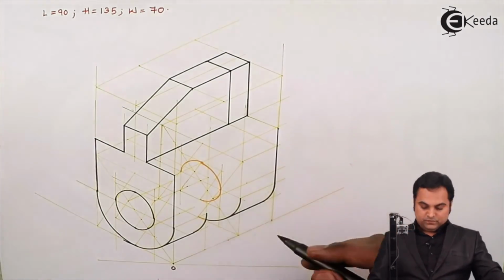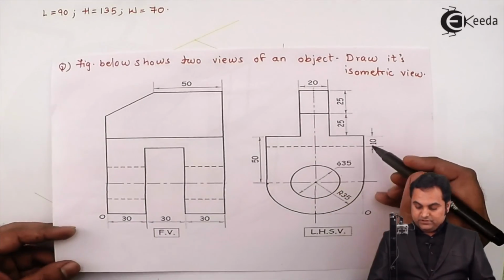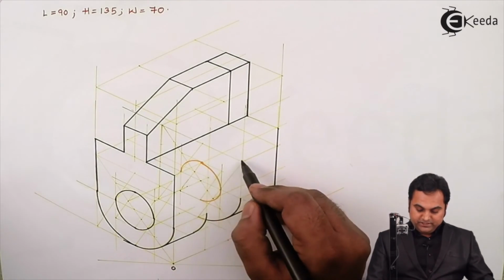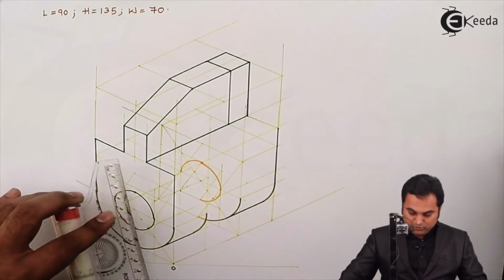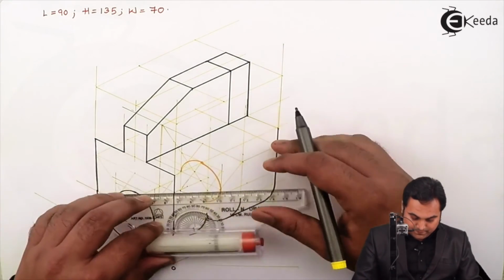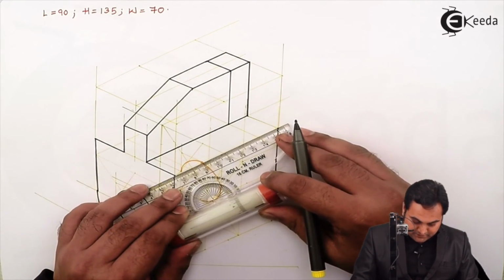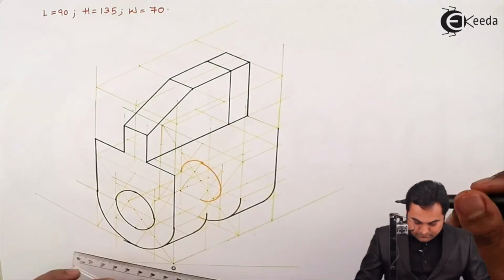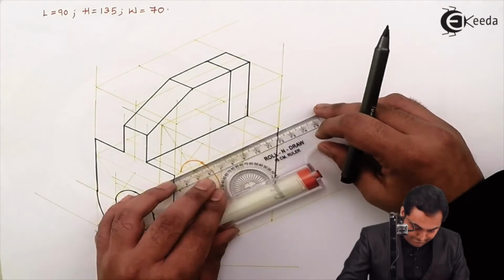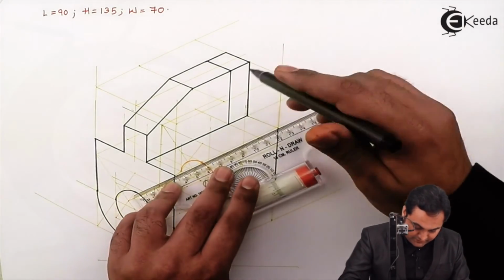And then from here also we have a 10 mm cut, that is, both these planes would be joined 10 mm below. So for that I am drawing a line at 10 mm parallel connecting these planes. Now it will be only up till here. So for that the top surfaces are connected.